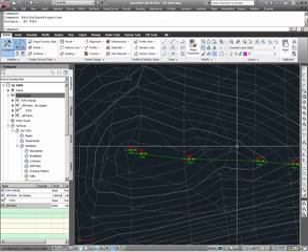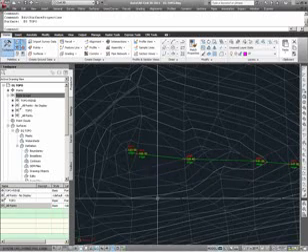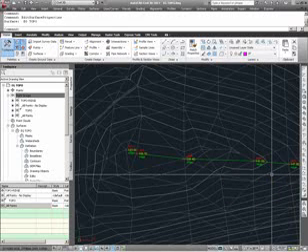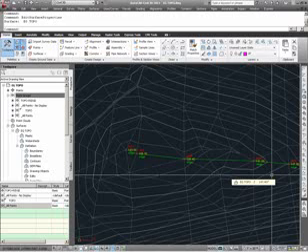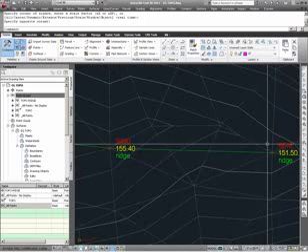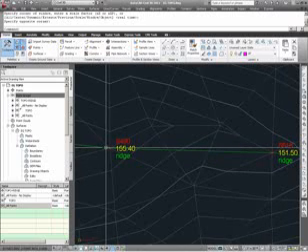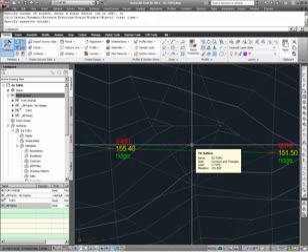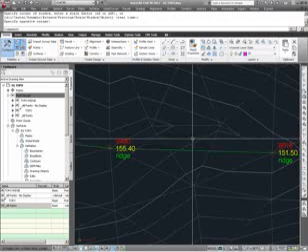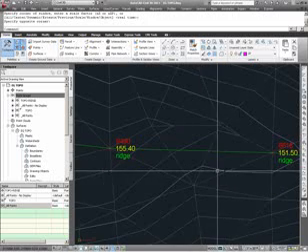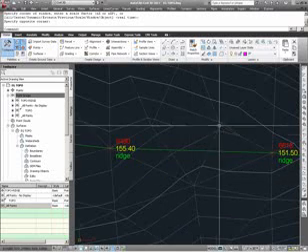After choosing OK, I can now see the triangulations in addition to the contours. So for this example, again, we are using feature lines to be defined as break lines for the surface, e.g. topo, in order to create a more accurate surface model. We can see that this is in fact necessary because looking at the triangulations, I can see a ridge point here and a ridge point here. And this being the case, there should be a triangulation line which connects the two in order to model that ridge and get the effect that the grades within this vicinity would be sheeting away from this ridge. Here, since we have not yet defined the ridge as a break line, we can see that the triangulations are incorrect and that they are crossing the ridge.